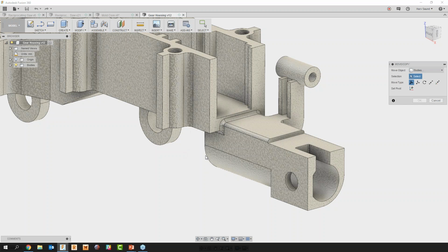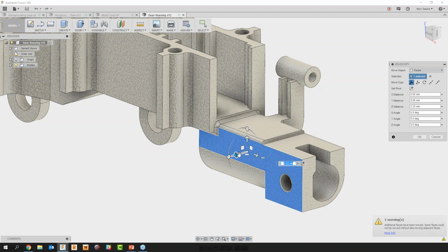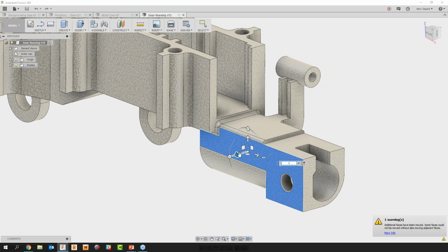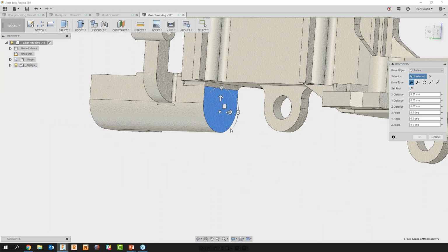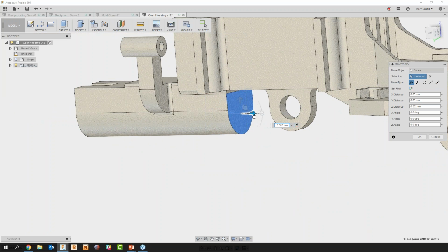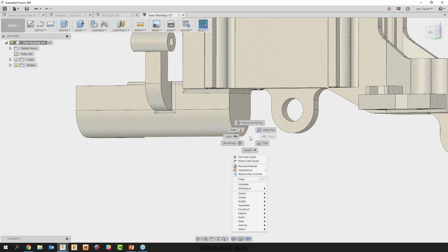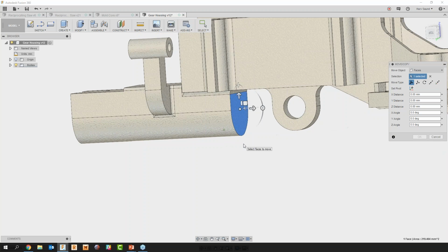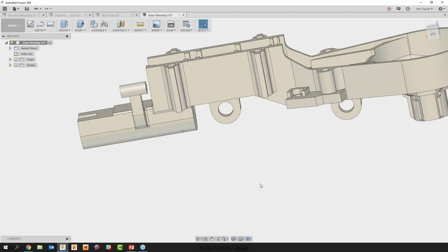What we can do within Fusion is use what we term move copy. This will allow us to quickly and easily pick up on specific faces in that design and just grab and drag. This allows us to quickly and easily develop that design to being exactly what it needs to be, giving us that real fluidity within the design process. So if I want that to be, let's say, 8 mil or even more, we can quickly and easily generate the kind of structure and design that we're going to be working with. So let's increase that by a further 3.5.